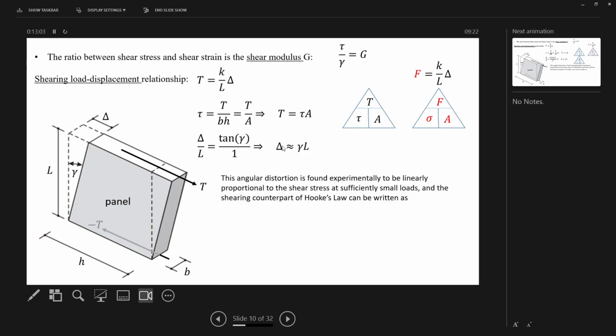So if we simplify delta, meaning a millimeter displacement, divided by L equals that, then what we're getting is delta is approximately gamma L. Okay? So just go with me on that, and it does work. And then it's all done?